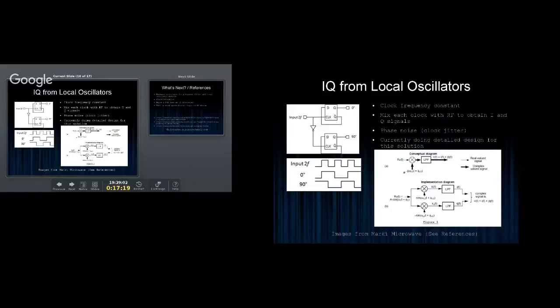But as far as the theoretical model is concerned, your 10 megahertz or maybe your 20 megahertz signal, if you've converted up to 20, comes in here, and you put in your in-phase and your quadrature signals. As part of that down conversion process, you impart that quadrature upon your RF signal. And then you low-pass filter it because you have harmonics from the square waves that you've just mixed with. And then you can digitize the I and the Q, in-phase and quadrature.